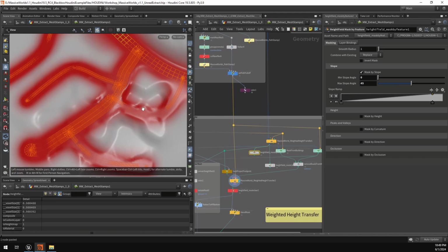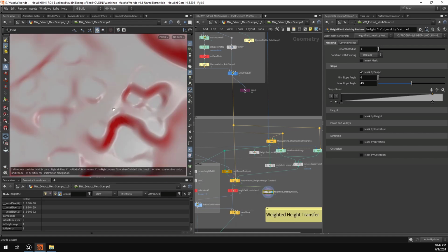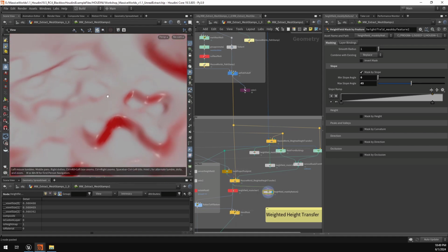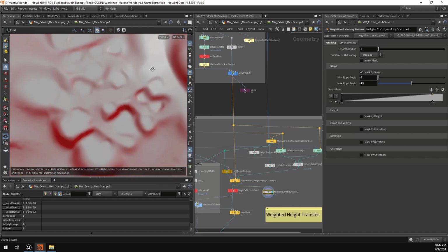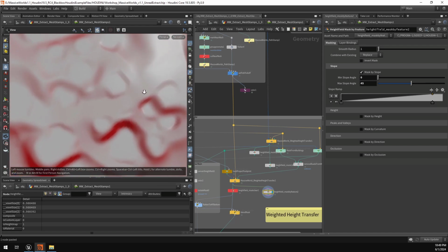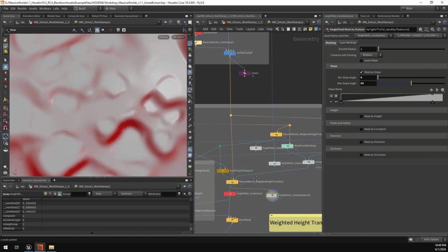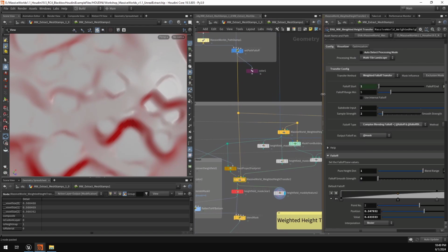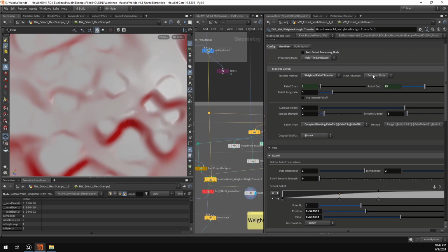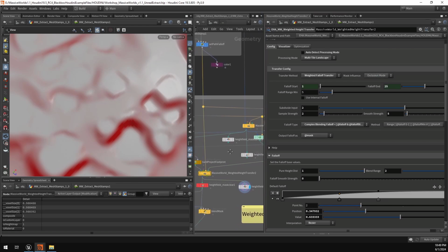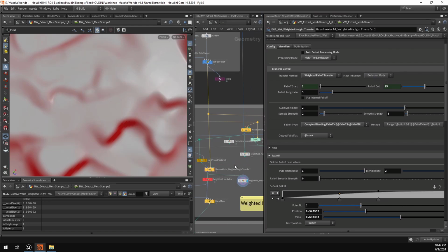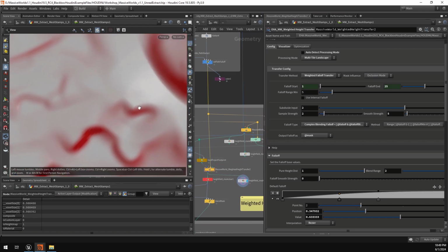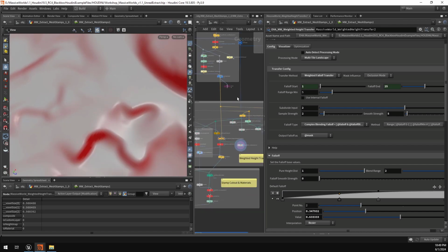At the same time though, I do want to make sure that the roads are as smooth as possible. So if I grab this mask by feature node again and I drop it over here, notice how we have a nice transition where the roads are nicely smooth and they're not interfering with the buildings. If we didn't have this mask set up here, which is set up right there under mask influence, and if I were to disconnect this, then our roads would actually eat into the space of our structures.